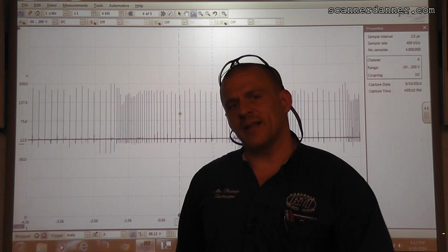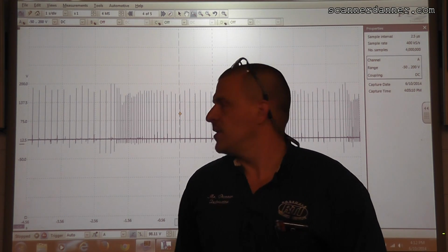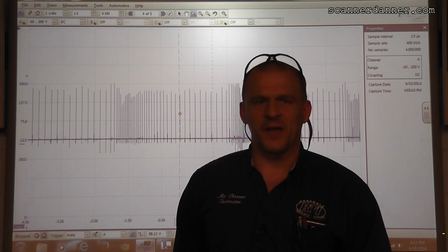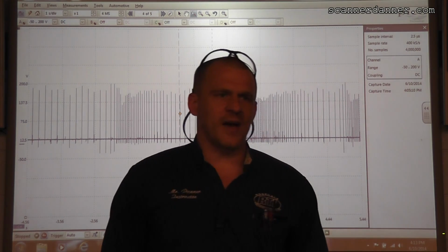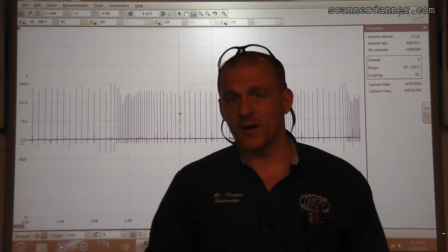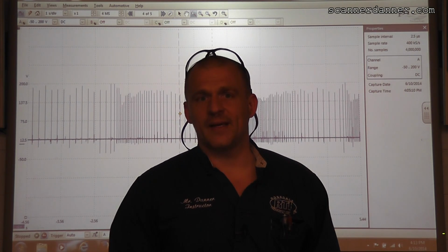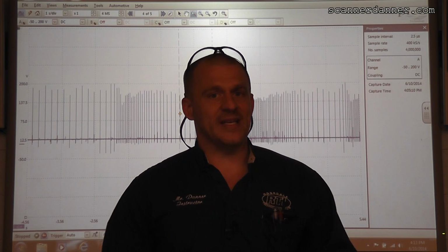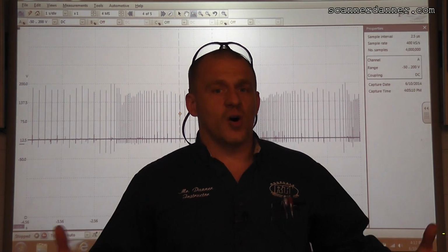But I hope you guys liked what I just covered with you as far as it relates to time base, the waveform buffer, and the sampling. And again, to leave you with that comment with the sample, remember, if you increase your time base, you want to increase your sample rate if you want the detail with that longer time base.